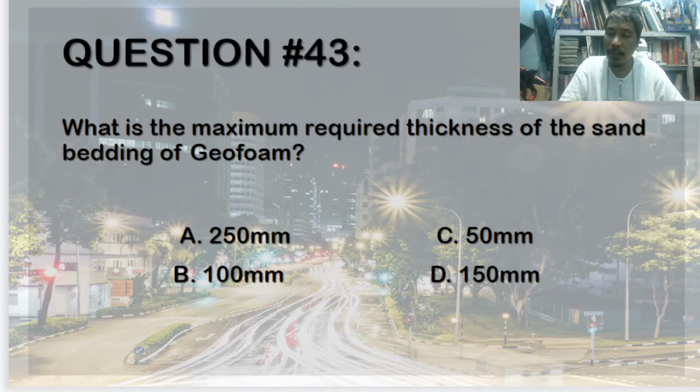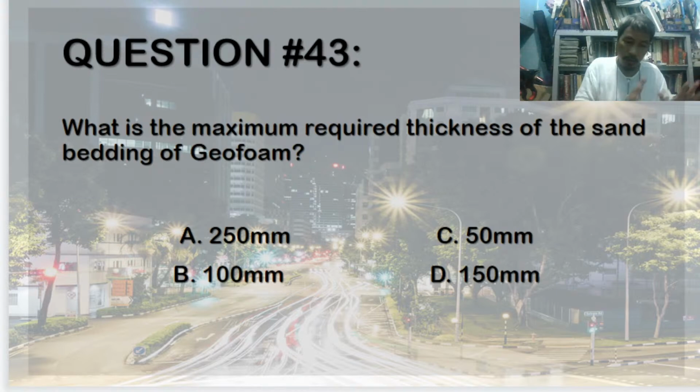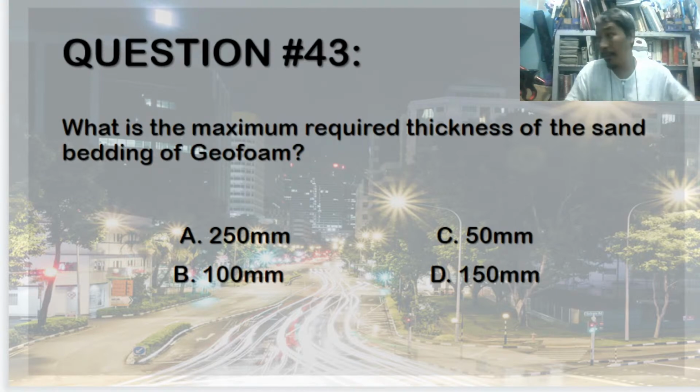Sand bedding means before you install the geofoam material, you first have to prepare the soil by using sand bedding. So, use about 150 mm.